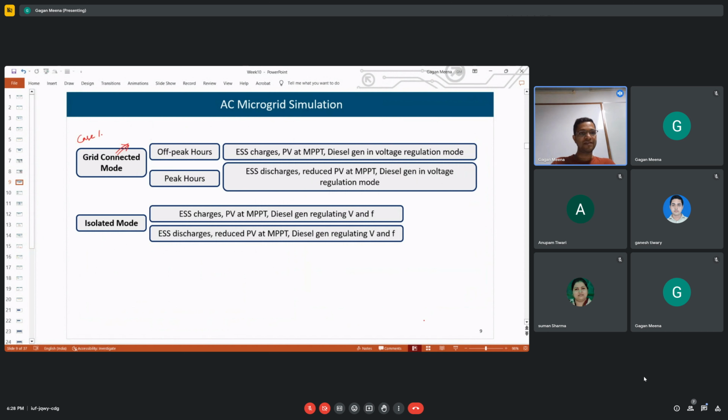But these are two DC sides, right? DC means a transformer is not applicable, it needs an AC component. Yes, but although this side is DC, the output of this active bridge is AC, because this bridge is converting DC into AC. This is also converting DC into AC. So in between we have an AC interface, and on both sides of the transformer we have AC only.